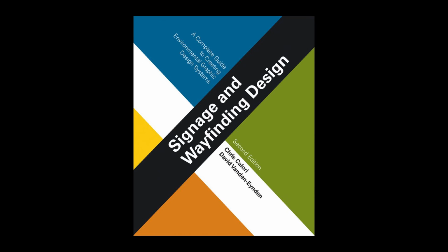Mounting pins for individual cut or fabricated letters or for heavier sign plaques are often secured with adhesives or mechanical parts into pockets drilled into a wall. Large and/or heavy sign units often require connection into a building's underlying structural system, which can be inches or sometimes feet beyond a ceiling or wall surface.